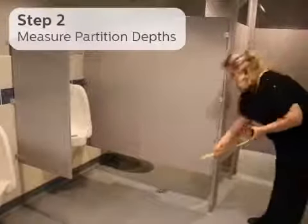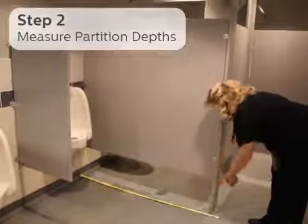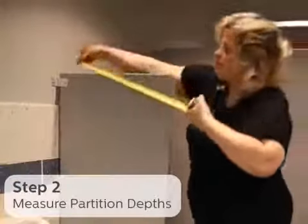Next, step 2, measure the partition depth from the back wall to the front edge of the pilaster. Make sure to measure any urinal screens as well.